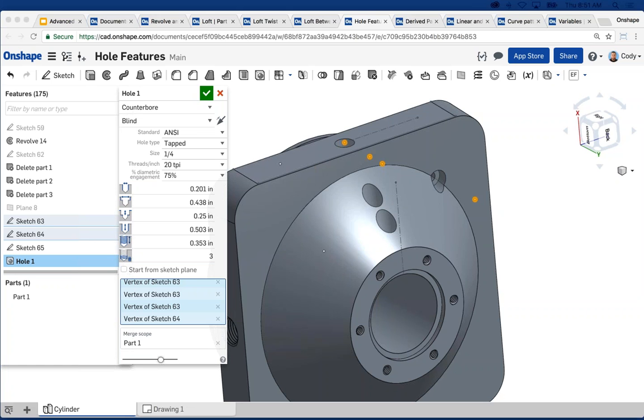Questions. This is a question: how do you sketch the transition between the blue and yellow-orange on the mouse? It's the join of two extrude features. So you create two extrude features, extrude them in both directions, and where they join creates an edge. Could you show how to create a loft between a circle and a rectangle by matching the vertices? It's very similar to what I showed earlier, so forgive me. This will be recorded, so you can go back and watch that first example, by the way, which is a rectangle to circle transition.